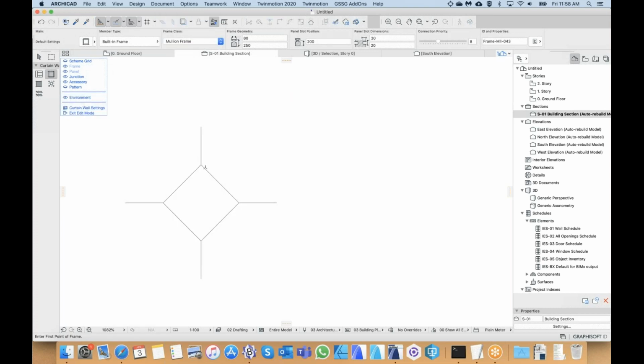And now we're going to draw over these lines. When we see a tick, it's on an end node. So I'm going to click on a node, and when I see the black pencil, I click again. We'll see some pink lines, but we can ignore them for now. I'm just going to draw over each of these lines, making sure that we connect to the nodes. We just have to do one by one, connecting the points.